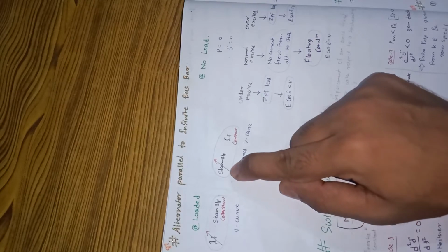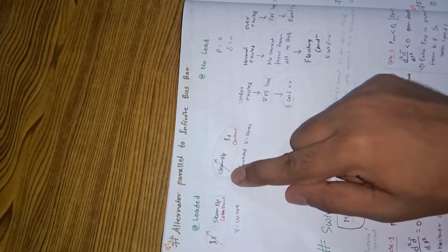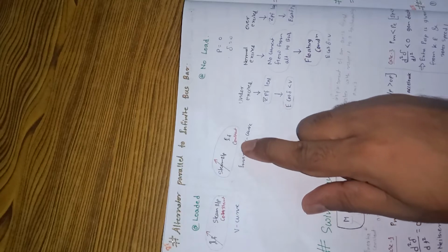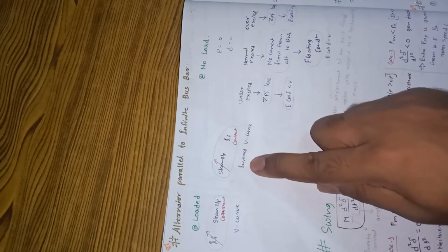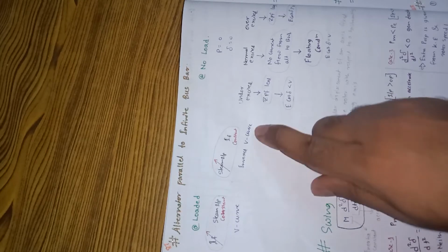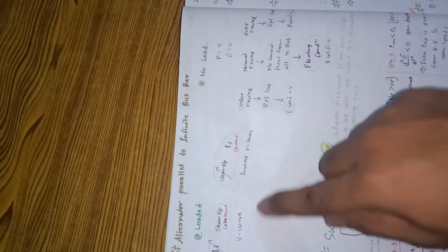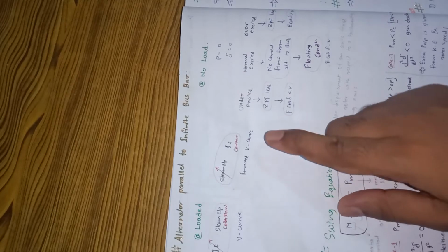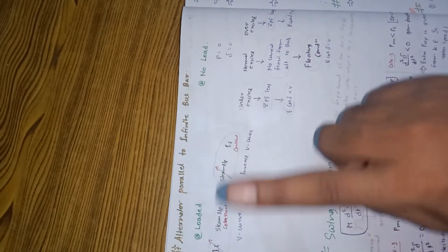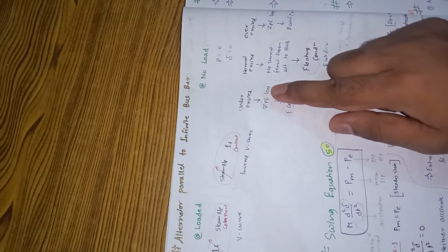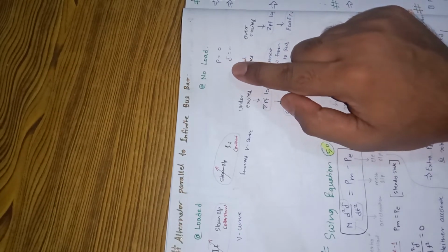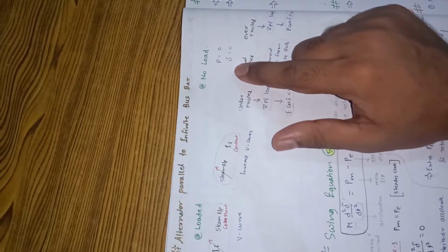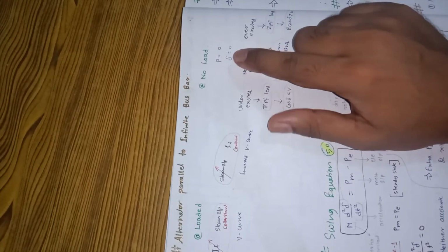Okay, and when we vary the steam input with field current constant, then we will see the effect of the inverted V curve. This is the only thing we need to keep in mind, and we can relate to the V curve and inverted V curve as we have studied before. Okay, and when we talk about no load, when they are not loaded but they are connected to the infinite bus, what will happen?